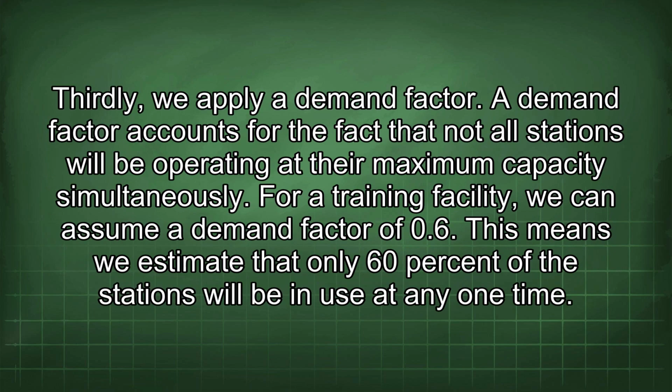Thirdly, we apply a demand factor. A demand factor accounts for the fact that not all stations will be operating at the maximum capacity simultaneously. For a training facility, we can assume a demand factor of 0.6. This means we estimate that only 60% of the stations will be in use at any one time.